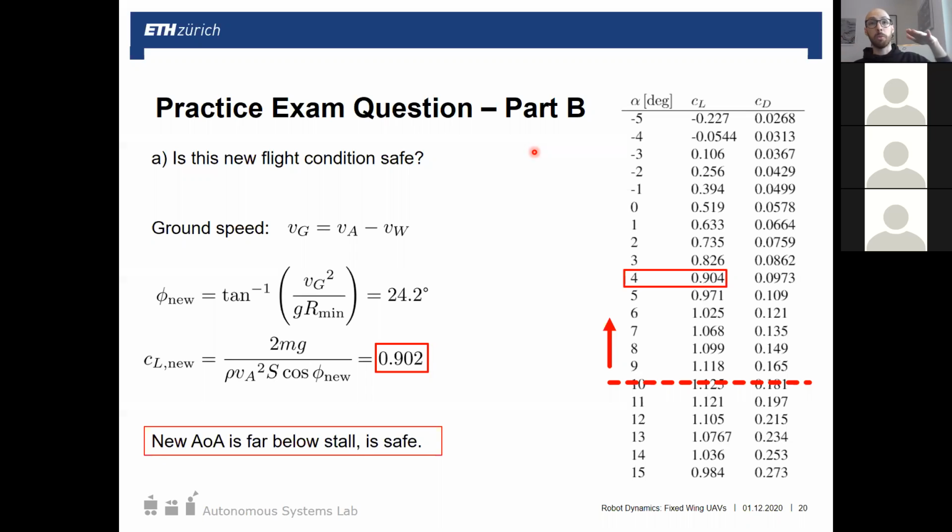In reality, how does wind actually interact with the plane? As it's ramping up with a gust, for example, there will be some kind of aerodynamic force exerted on the plane. But as far as our flight speed through the air mass, once that wind is stable and we've already compensated for this additional force, it behaves really similarly to just a velocity component. So that's why we model it this way.